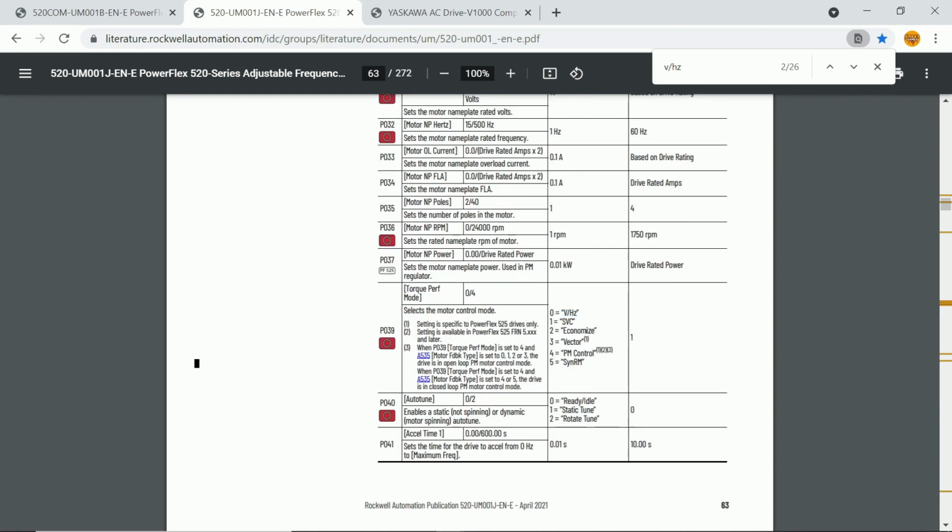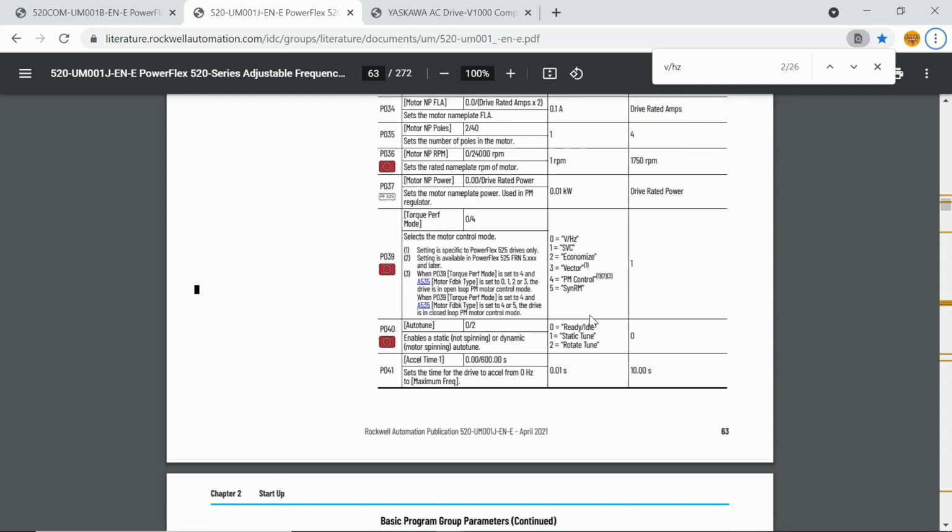Generally, this is where we get our volts hertz part, but here, by default, we already have our number 1, which is sensorless, where it's decided by precision, torque, and low velocity, okay? So this is set by default. But if we wish to have more velocity, and you see that there's not really a big increase for velocity, and there's a minimum load, then change it to volts hertz, okay? Now, this is an advanced and important parameter.